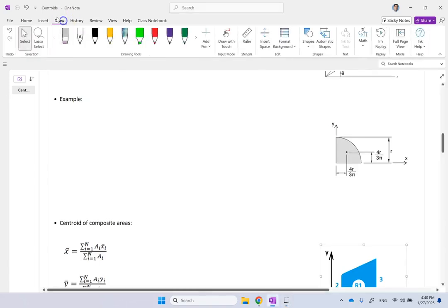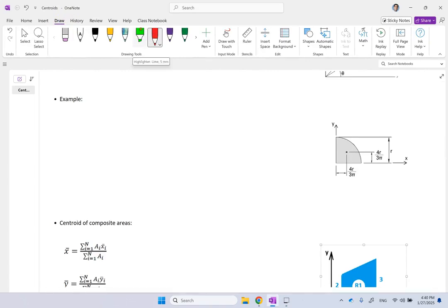Well, if I want to use the formulas I just had for the xy coordinates, then what I need for x bar is to go to a location x, or for y bar go to a location y, and draw either a vertical bar or a horizontal bar and let it sweep, right? So let's say, for instance, y bar. So for y bar, I have to come to this location y and then draw some small thickness dy, and that is going to be your dA element.